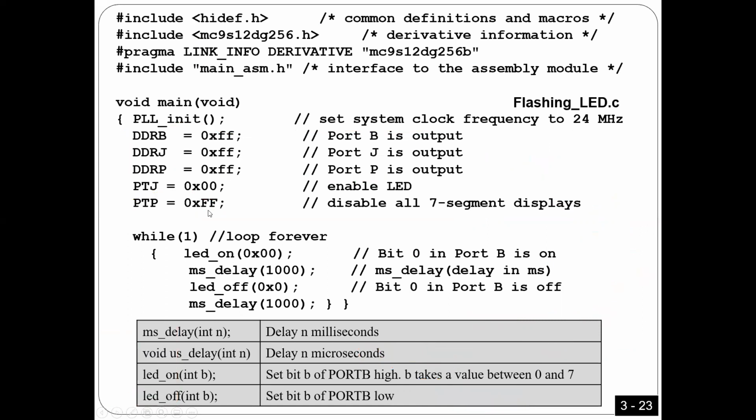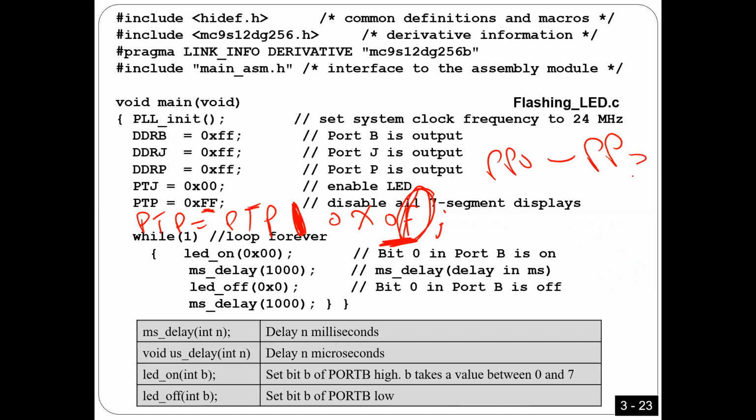For example, here I want to set 4 bits, and I don't want to change the other bits. The way I can do it, guys, look here. I can say PORTB is equal to PORTB, and because you want to set some bits, you have to use OR with 0x0F. That's it. So if you do something like that, I'm going to set the first 4 bits, PB0 to PB3, but I'm not going to change the other bits, PB4 to PB7, because they are connected to RGB, and I don't want to change the RGB now. I'm going to explain later what RGB and LED are.